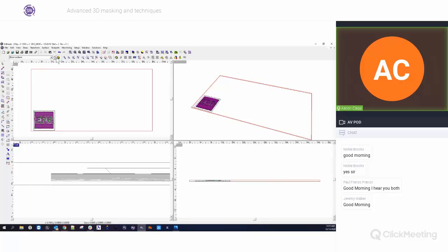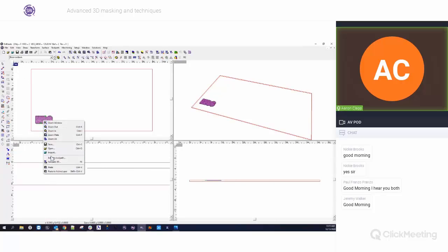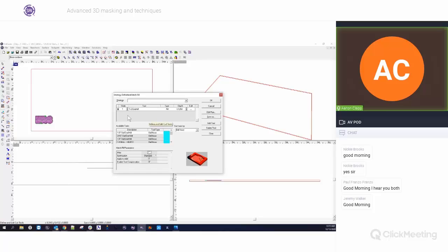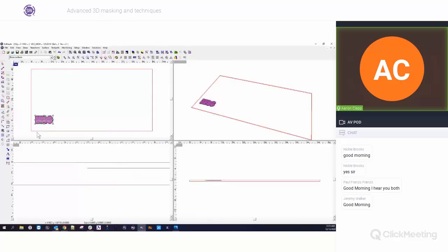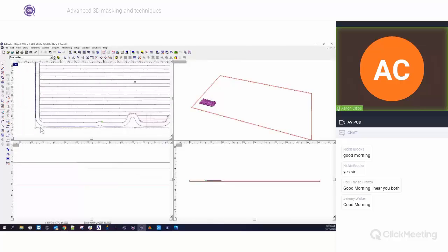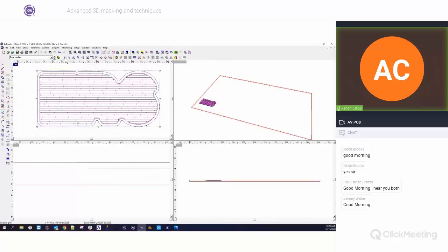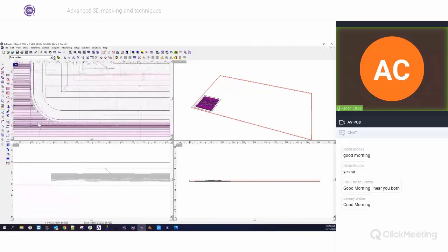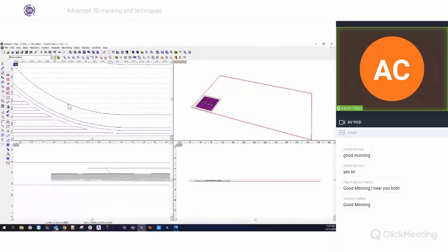So let's go back to our toolpath here, and we go to Edit Toolpath. This is a basic toolpath. So the first thing that's going to be cut is probably the 3D relief. I'm going to cut out the 3D relief first to give us this nice little platform. Then I'm going to come back and take my 1/2 inch end mill. It's really hard to see, but if we turn on all layers and look in real close, you see the difference between the lines here.